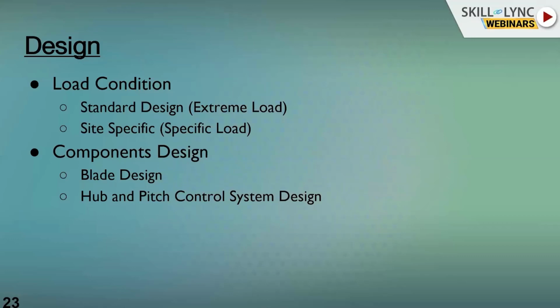And the component design. Component design: the blade is a separate technology, composite material. The design of the blade is not possible in a single-step mold. Smaller blades, up to 250 kilowatt, are possible to take out in a single mold. But if you are going for more than 250 kilowatt, and nowadays blade lengths have become 100 meters, 120 meters, available in the market, it is not possible to mold in a single stage. You have to go over 3-4 stages, internal stiffness, profile. Based on the profile, we have to give the longer chord length and all.